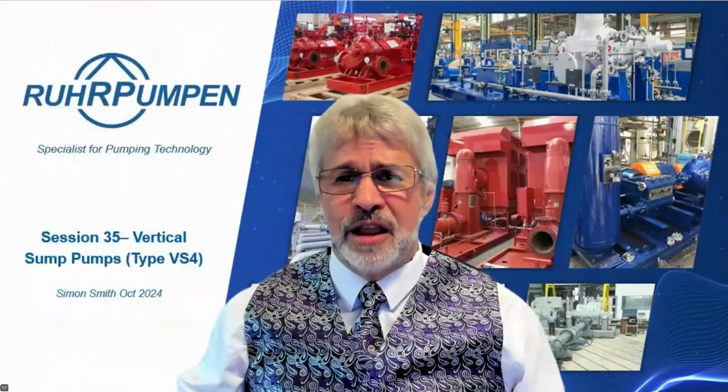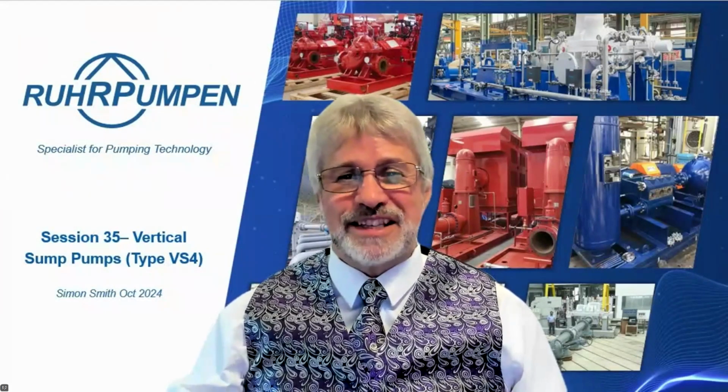An NPSH test would be an expensive test to do on a VS4 pump, just because you need a vacuum suppression tank that's going to be able to take the pump in through the top. So it's a bit messy. That is what we do on VS6 pumps because it's absolutely essential on an API 610 VS6 pump, but it's not really a necessity on a VS4 pump.